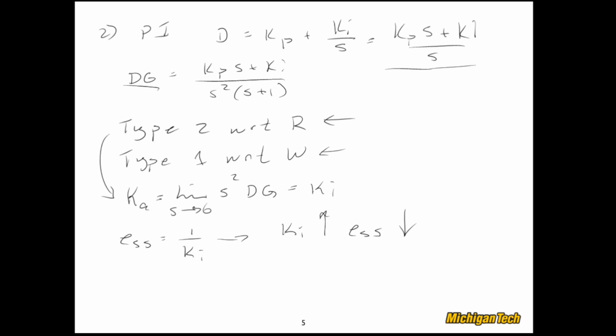Great. So the integral action, the integral term in the PID controller, improves our system type, gives it better disturbance rejection properties, better tracking properties, and it has the same qualitative effect on the steady state error that we do get, that as we increase Ki, we'll drive down steady state error. But now let's look at the transient response. And what we'll do here is just look at Y over R, the reference transfer function.